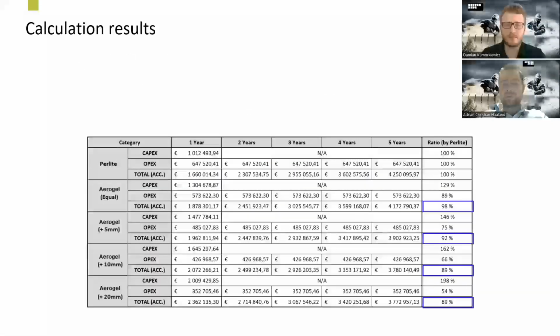Then, when we establish the right material to use, we start calculating the lifetime cost, capex and opex, for different thicknesses. So we have these large spreadsheets. We try every different insulation material, every different insulation thickness for every piece of equipment. Of course there's a tremendous amount of factors and variables playing around, but this is all happening back-end in the Excel sheets. So it's quite quick calculation, even though there are incredible amounts of variables.